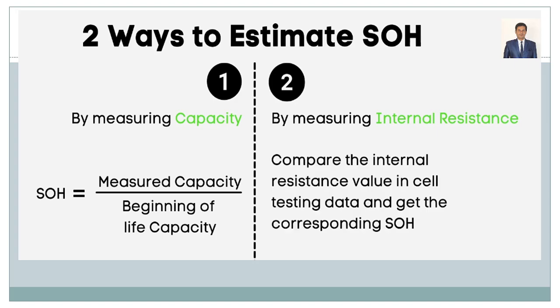If the resistance also increases, what will happen to the batteries? The battery life also will decrease, right? So that is what you talk about with the internal resistance of the batteries, right? So how does it make an impact on the BMS, right? So 50 milliohm, that is when you take this data for the testing, right? After 1 or 2 years, right, the resistance has increased from 50 to 90. So what will happen to the Q value?